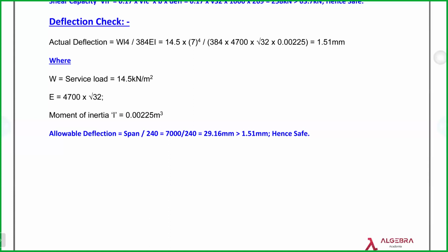Then you have to lay first for the longer direction. You understand? If you make it in reverse, longer direction first, shorter direction second, the slab will directly deflect. The shorter direction is the one which is going to carry the longer direction reinforcement, because my moment is completely based on what? Shorter direction. You get my point.